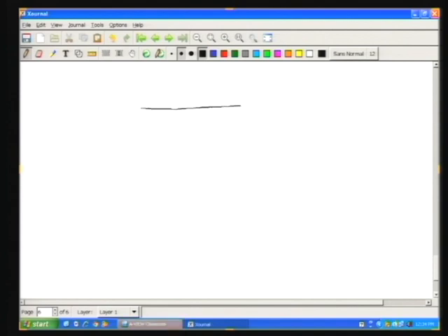Now, I will draw that figure again. So, this is the water level, this is a free surface, and quite often this is denoted by an inverted triangle with 3 lines below. This is a symbol which indicates that above here the pressure is P atmosphere. Now, let us say this is the curved surface and I had chosen a coordinate system where x is horizontal, y is vertical and z is also horizontal.